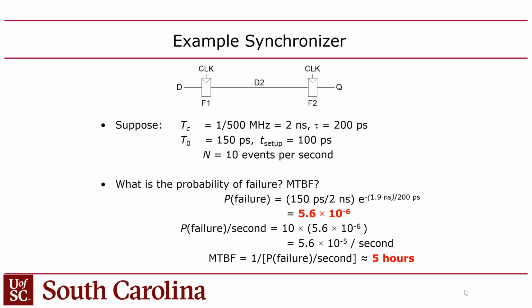Now to be fair, I think in a network card they probably have multiple synchronizers to try to reduce that even further. But there's always a chance, it's just the nature of the flip-flops. I believe they also have some checksum at the end. Yeah, there's also protocol level checking.